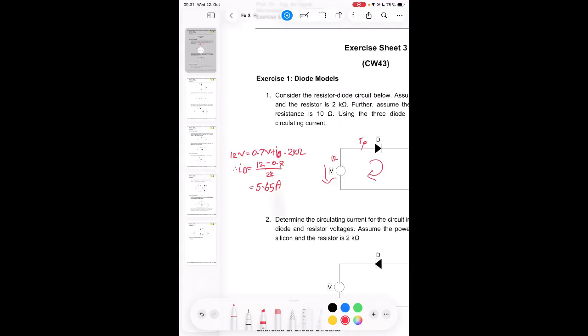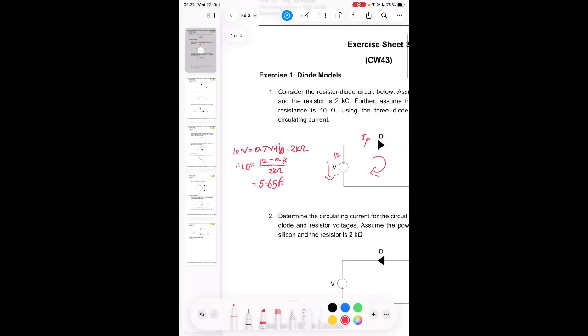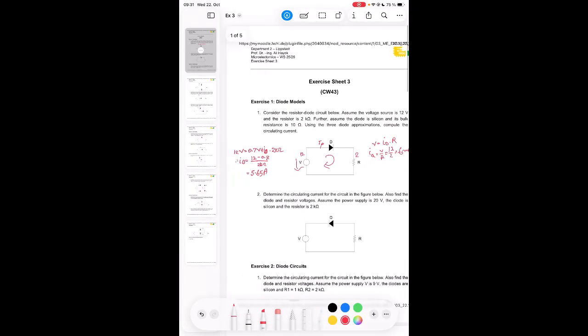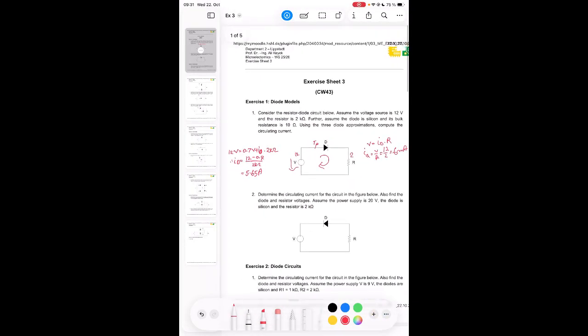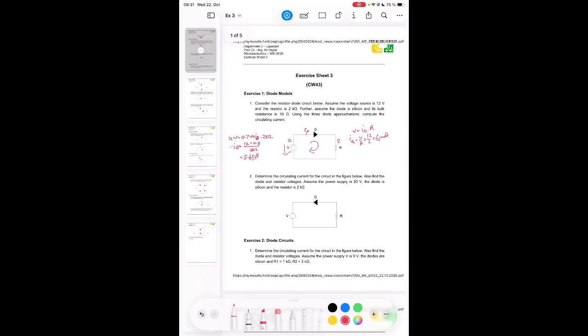And then if we just continue, we have in addition this 2 kilo ohm load resistor. Now again KCL, KVL, we have the same story. 12 volt is equal to 0.7 on this side. Very important, now we have the ID flowing through the load resistor, but also the diode resistor. That's why it's plus ID multiplied by RD plus R. This is actually the difference we have now.